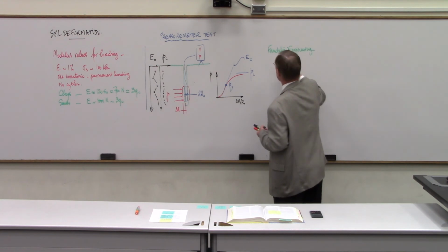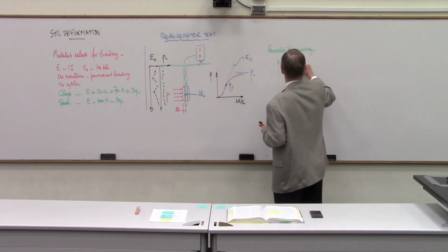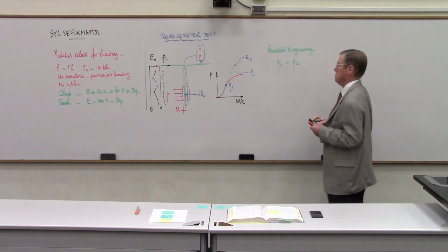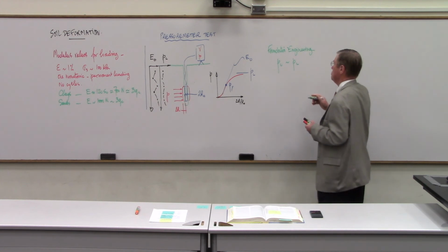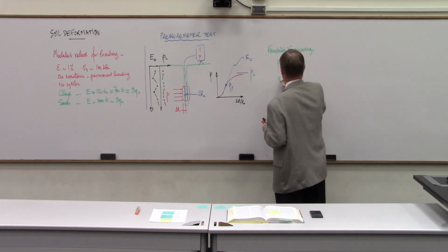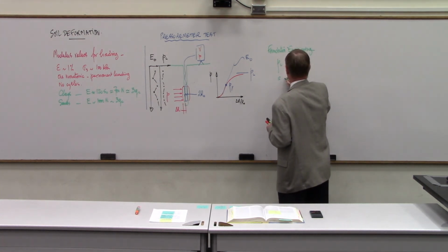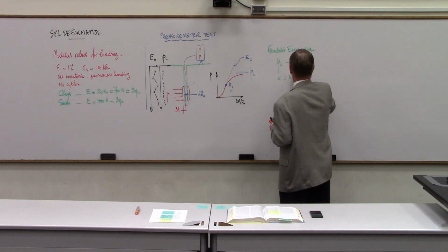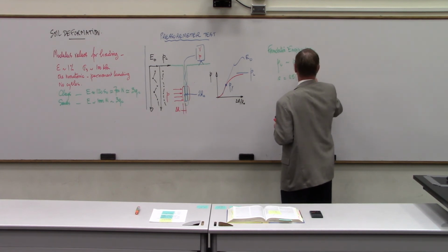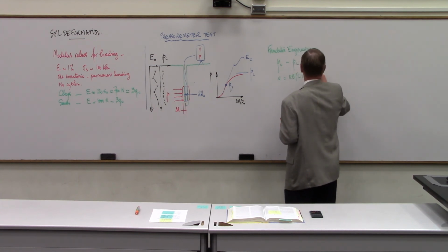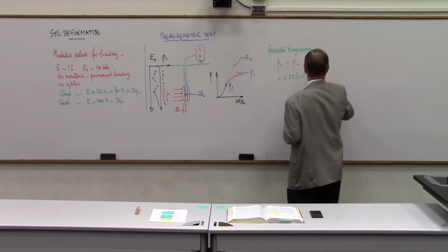And when it comes to bearing capacity, we will typically use P sub U approximately equal to PL. And then we use a settlement equation that is of the form, at least for rectangular footings, S equals 0.8 times (1 minus nu squared) P B over E.